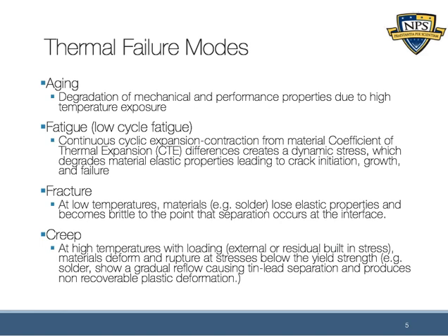Fatigue is the second one, in this case low cycle fatigue. Low cycle fatigue is continuous cyclic expansion and contraction from the material coefficient of thermal expansion. So that's a CTE mismatch between two materials that we talked about last week.